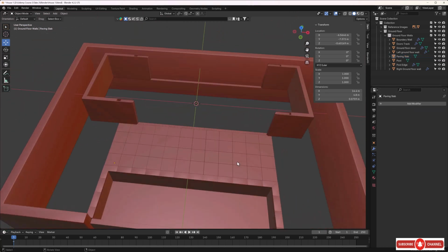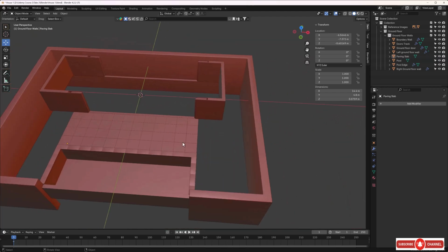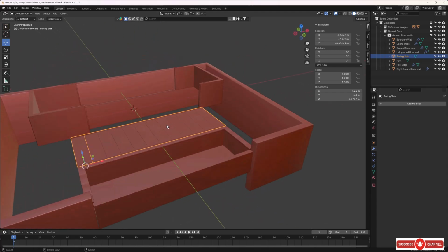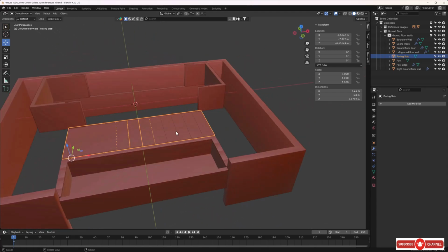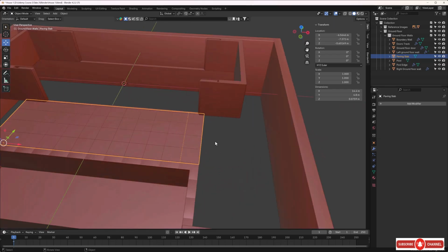Okay, so that's a fair portion of the paving slabs already done. So now we need to carry on in this direction. But this is one lump now. The array modifiers turn this into one lump. And that's pretty good, but we need a spare paving slab now, so we can start working this way. So let's get one from this.